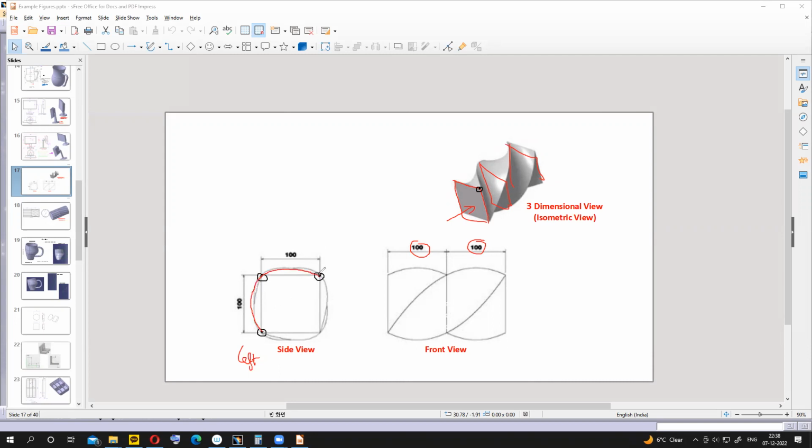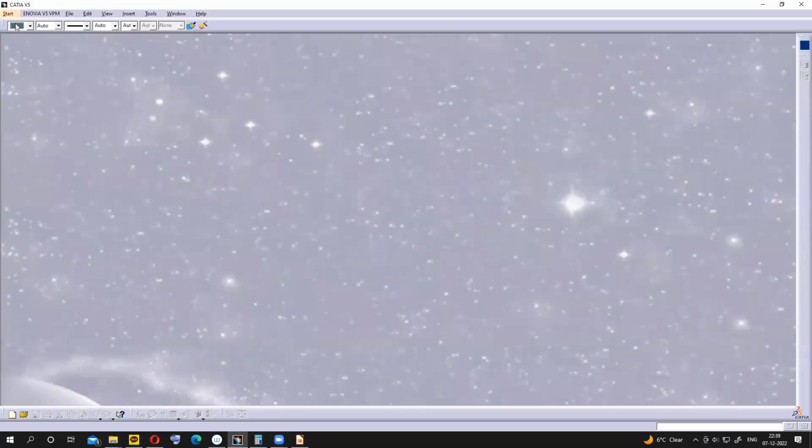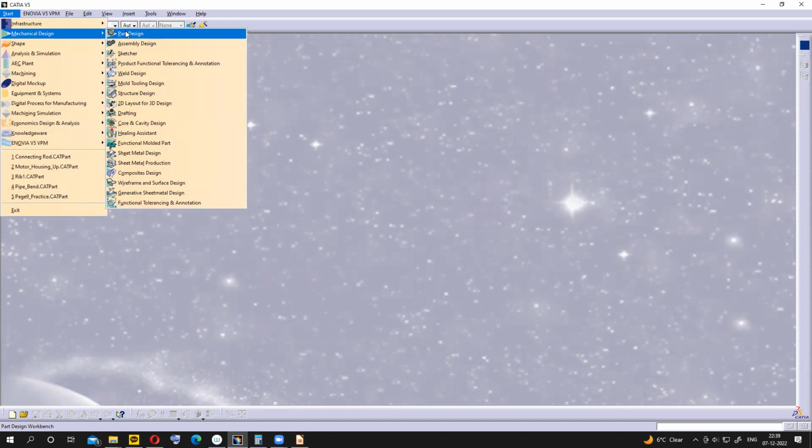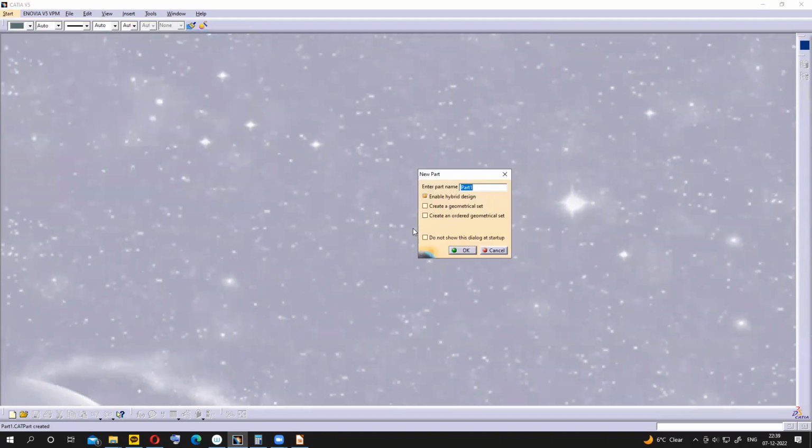When I see from the left side, you should change the closing point of sketch 2 to here. I mean, when you see the closing points along this corner, you should change to here, and then here. But in the figure, if it is a clockwise twist, and the closing point for sketch 1 is here, the second sketch should be here, and the third sketch should be another point. So that depends on the twist in which direction. Yes, so let's start with Part Design.